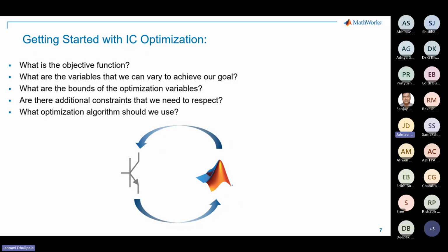When I say variables, for example, if I take transistor sizes, I would consider what its width should be, what the length should be, what the bandwidth is, and what my passive components' variable ranges should be, and what kind of limit I need to go with. Without a defined problem scope, you might end up with impractical solutions, like a capacitor size which is very, very large.